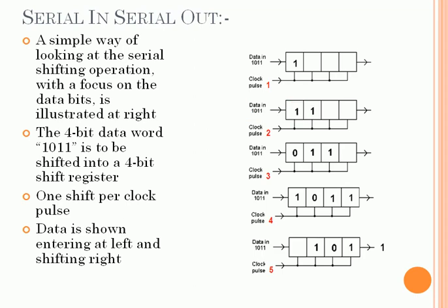And now we have left 1 0 out of the register, and this 1 1 is being stored in the register. At the third clock pulse, this 1 will be shifted into the next block, like you can see here, and this one is shifted into the next flip-flop, and the next 0 is being loaded into the first flip-flop.